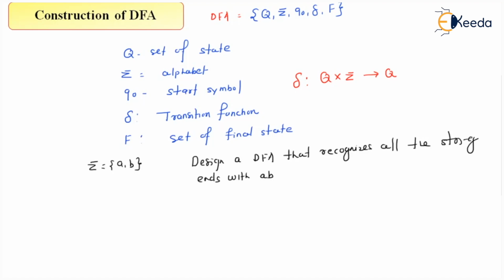Okay, so let's design this machine over here. Now here there are two ways we can design. One is the table part, and another one is the diagram part. I'm more keen on designing the table right now, and this is the starting point, that is the start state. Now there are two inputs, A and B. In the first case, I remember each and every alphabet. So the moment A comes, I remember that my last scanned input in this case is A. QS on input A is QA.